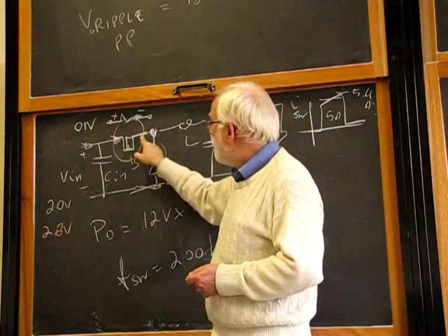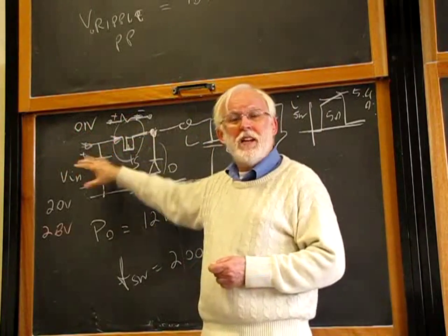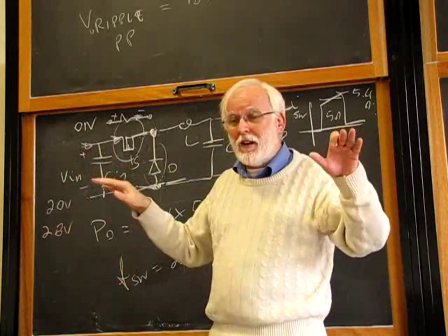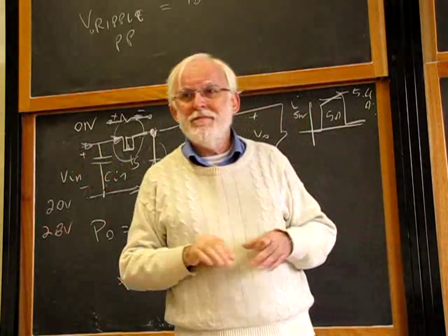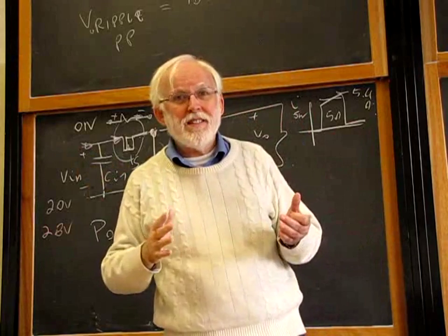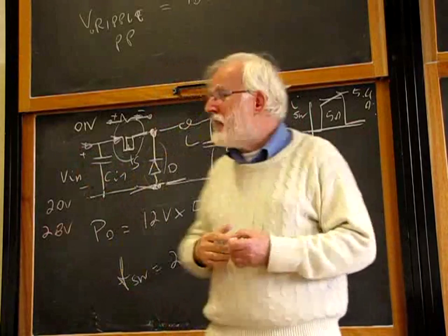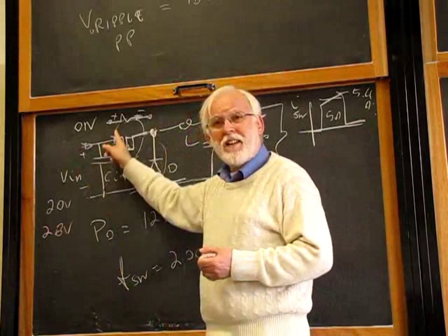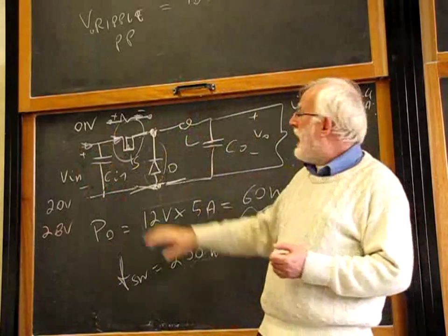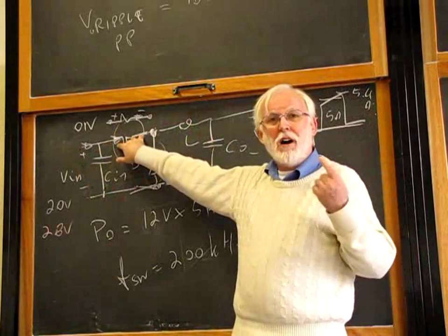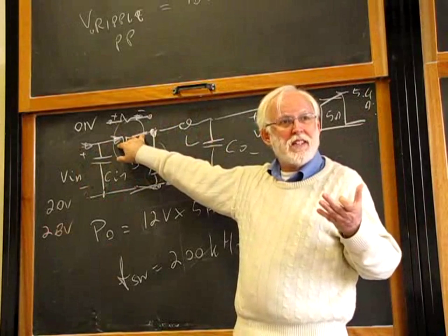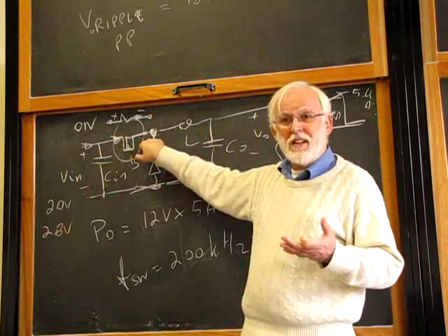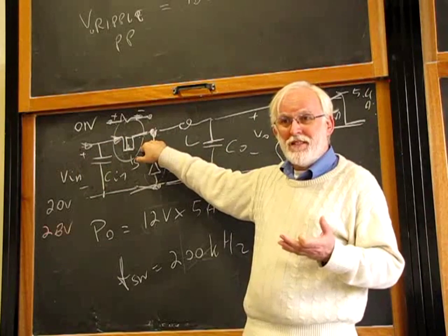Because remember, if here you lose 10% of the input voltage, you have 10% of your efficiency flying away from the window. Lost, just that. So if the minimum input voltage over here is 20 volts, and you put here a voltage drop that is 1 volt, 5% of efficiency is lost just on this switch, just on the voltage drop across the switch.